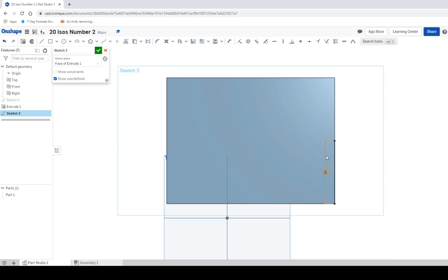If you hit the escape key, that line goes away. You can just click line again, and you can start the next line over this way. Click and go to the right, and make that 2. Hit enter. And then you can just connect the dots on the next part. Make sure that you actually connect the dots together. It should have this square with a little circle in here. That means it's going to snap into place. So you should have a whole triangle here.